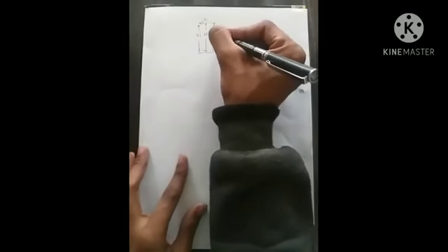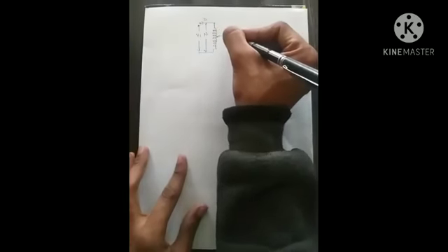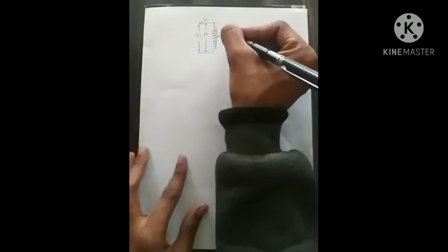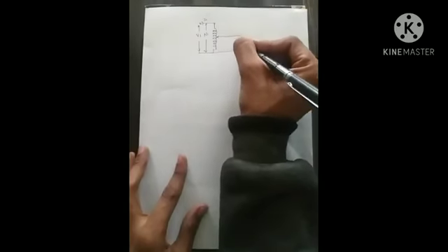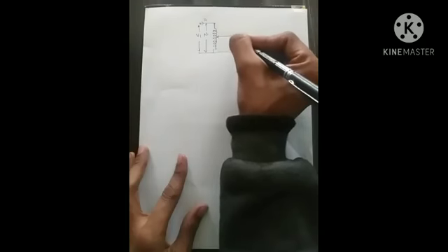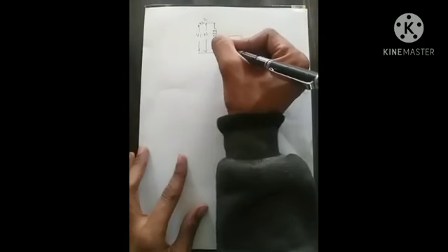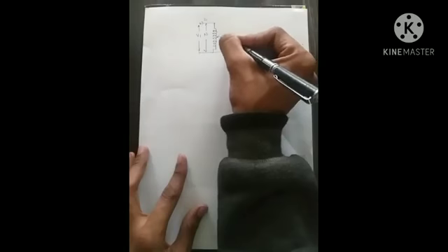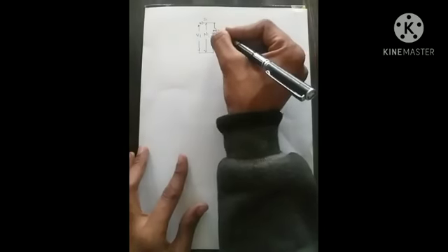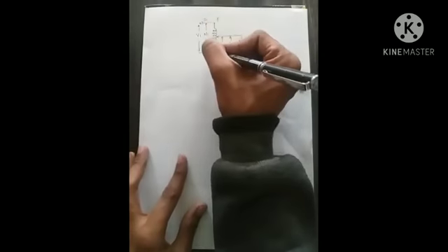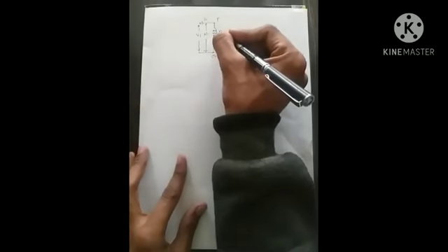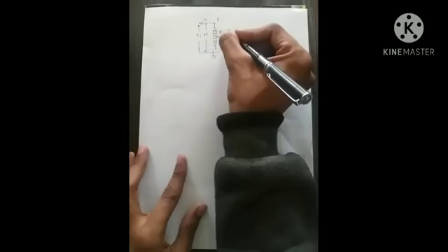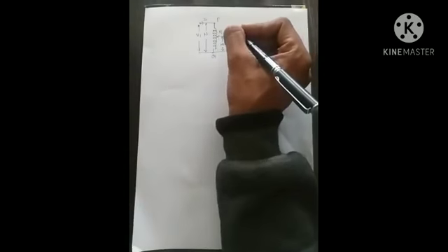The secondary winding of the single phase transformer is made by using a tapping connection on the main winding. After that, we have to draw here the load L, and the number of turns of the tapped winding is named as N2, and the voltage across this tapped winding is considered as V2. The full winding we will name PQ winding, and the tap is named R. The current flowing through the secondary winding is considered as I2.